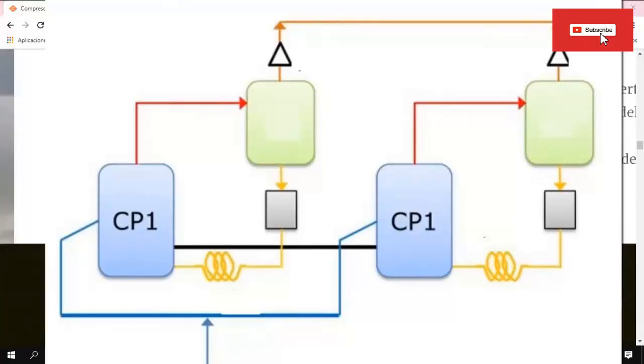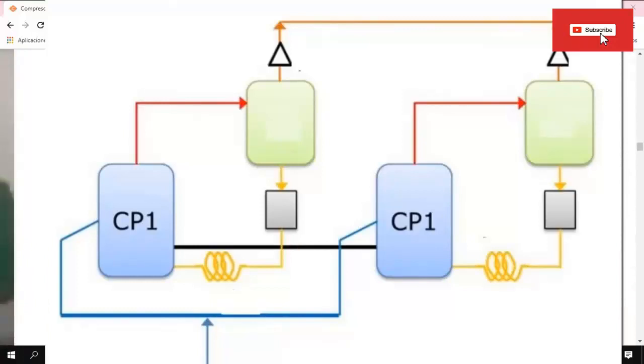7. The design of symmetrical suction pipes is not so strict. Oil return depends on the efficiency of the oil separator, not the flow of suction gas. The efficiency of the oil separator only needs to meet the running condition of a single compressor.